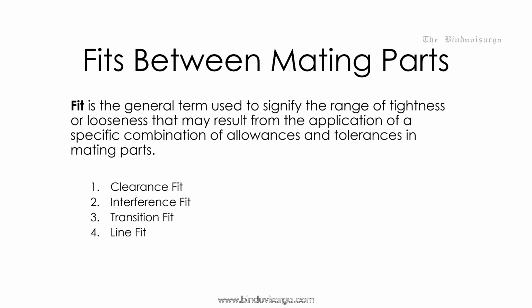Fit between mating parts. Fit is the general term used to signify the range of tightness or looseness that may result from the application of a specific combination of allowance and tolerances in mating parts. There are four types of fits in mating parts: clearance fit, interference fit, transition fit, and line fit.